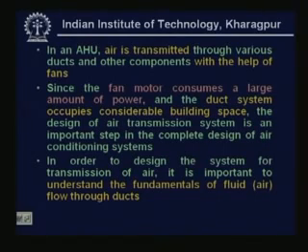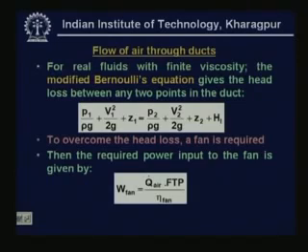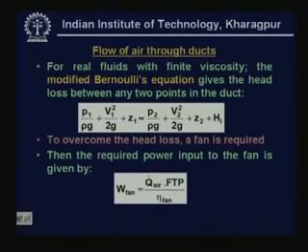So, let us look at the fundamental equations. These aspects I have discussed while discussing the fundamentals of fluid flow. Okay, so I assume that you still remember those things. So, straight away I go to the governing equation, which is called as modified Bernoulli equation. You must remember the assumptions under which the Bernoulli equation is valid. Okay. So, for real fluids with finite viscosity, the modified Bernoulli's equation gives the head loss between any 2 points in the duct.